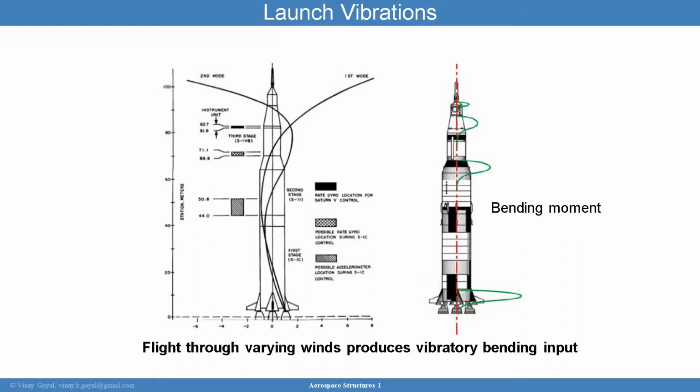Very similarly for a launch vehicle, I'm looking at the same situation. I'm looking at running Monte Carlo simulations, or many different simulations, to determine what is that statistically meaningful 99/90 load that I need to design my structure to. And that's going to vary as you go through the length of the vehicle, because the bending loads could impart various loads through it.